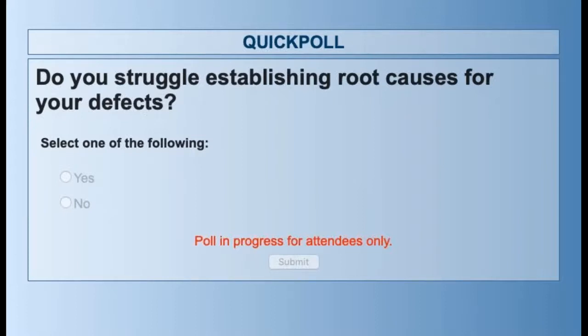This in industry is quite a problem that we're faced with. We can see in an injection molding process maybe some splay, or maybe there are structural defects or integrity issues on the part, and we're really trying to figure out, was that the material, was that the heating process of the mold, was that the cooling process in the molding? We really don't know, so we start just turning dials and changing things in the hopes of landing on the solution to that process.